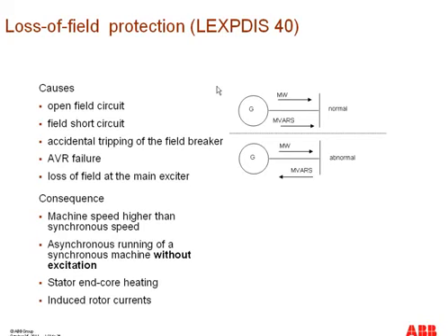So there can be different reasons for this loss of field, and the consequences would be quite enormous: speeding up of the generator and asynchronous running without the excitation, and some heating will also be there for the end part of the stator.